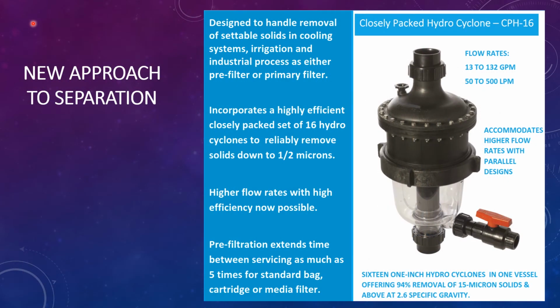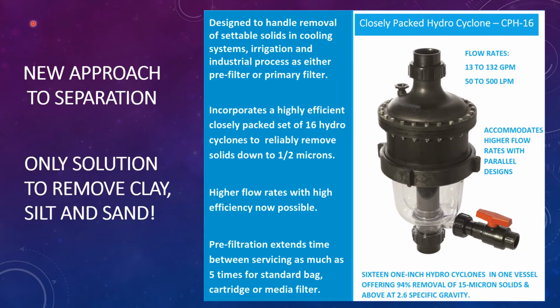The previous two separation technologies that you saw only provide removal down to 74 micron reliably. So this is a new approach that will remove clay, silt, as well as the sand. And so it's quite a new breakthrough. It operates over a wide flow range, where those other two technologies have a sweet spot.